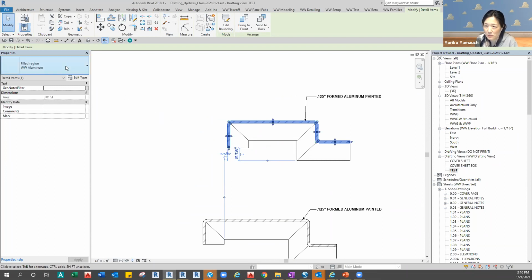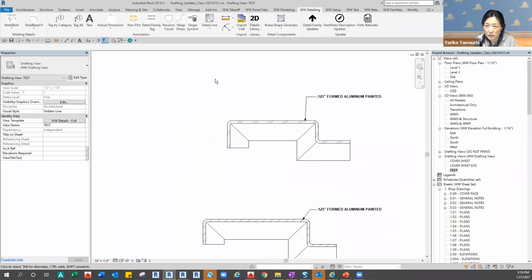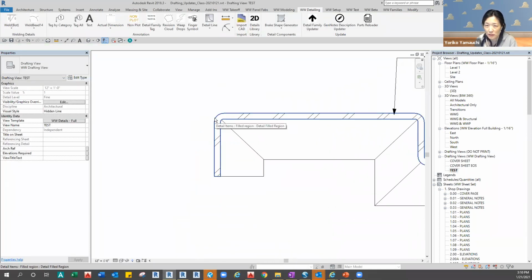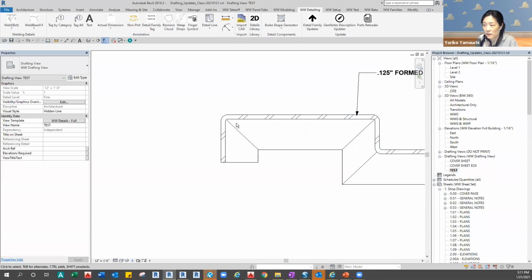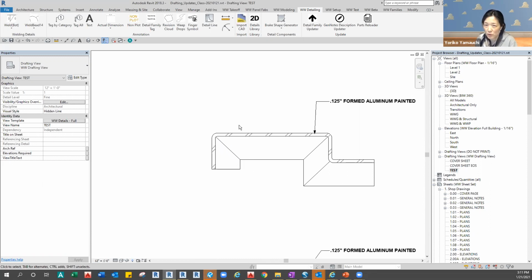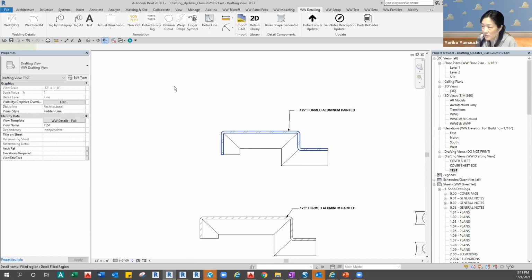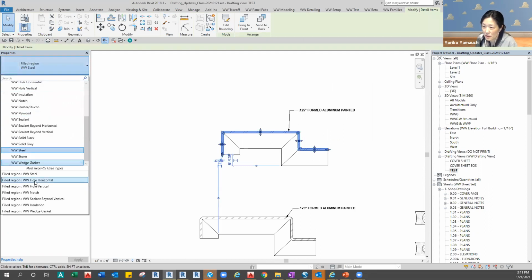And then the common mistake I sometimes see, and I'm probably too picky, is that sometimes you have to switch from aluminum to steel. Then you have to be careful because when you bend steel or aluminum, the radius of the corner is different. So if you switch it, you may give the fabrication team incorrect information. If you really want to show the correct one, I would recommend you redraw with the correct component or correct materials. That's the only stuff I sometimes see in shop drawings.